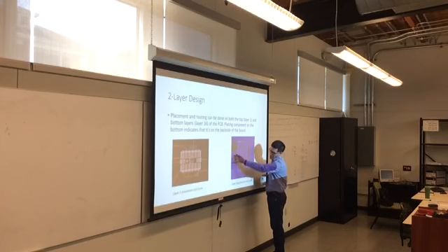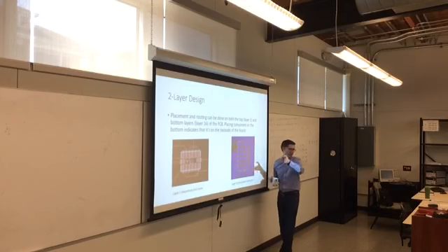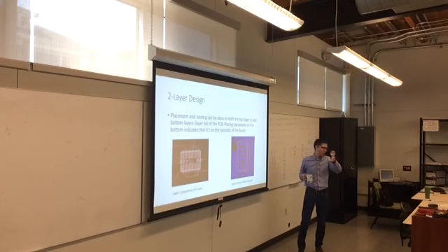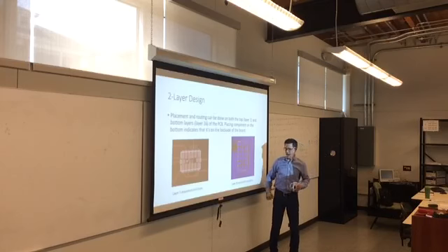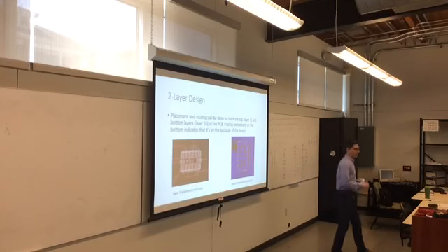So if this big blue area here is ground, and these are my 2 ground pins, I just go boom, and dump them down to the ground pin of the board. It's like on a car where the frame is ground, and that's what you're connected to. So you can have an easy ground point everywhere. It's the same thing here where you just have a pour, and that becomes your ground.